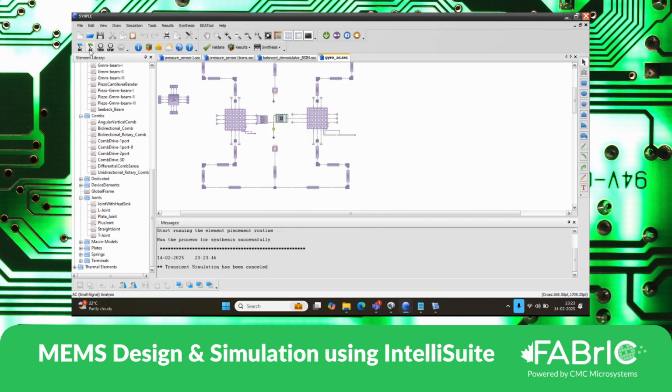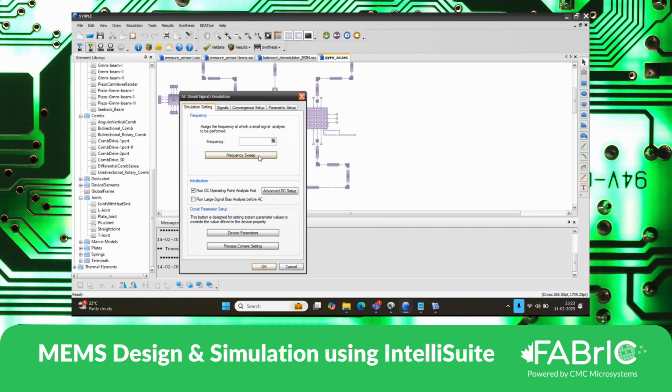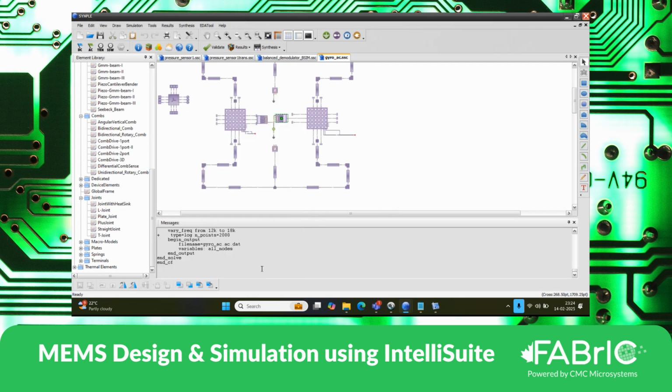Let me show you the output of this. I have designed this for 15 kilohertz. There is a document to learn this. I want to run the simulation between 12 kilohertz and 18 kilohertz with 2000 points on a log scale, and I get a resonance curve. This is purely AC based, that is, I'm trying to find the natural frequency of the device.